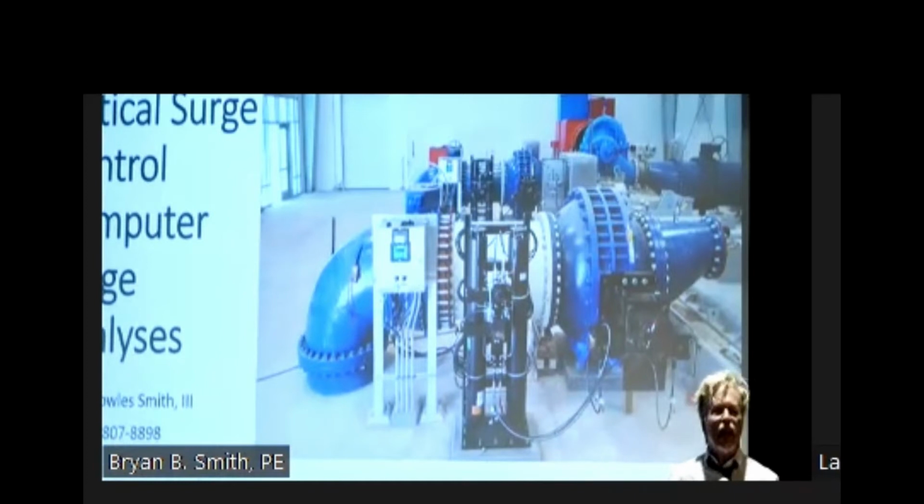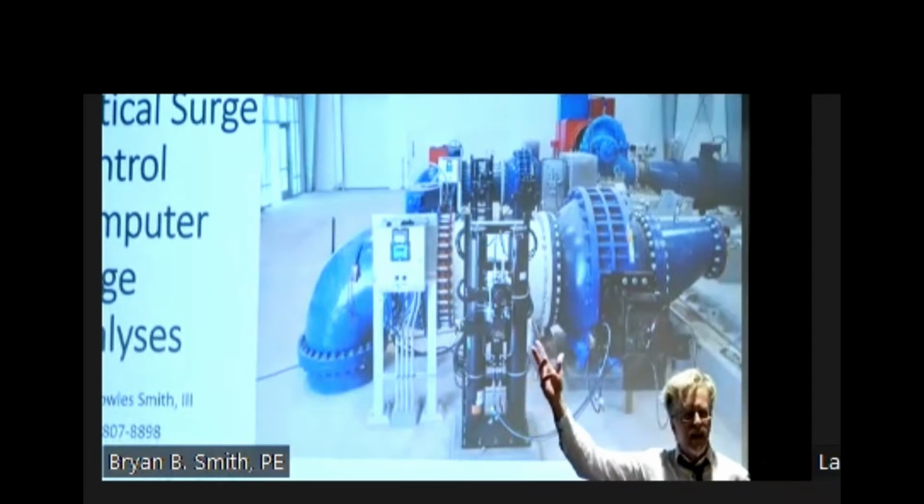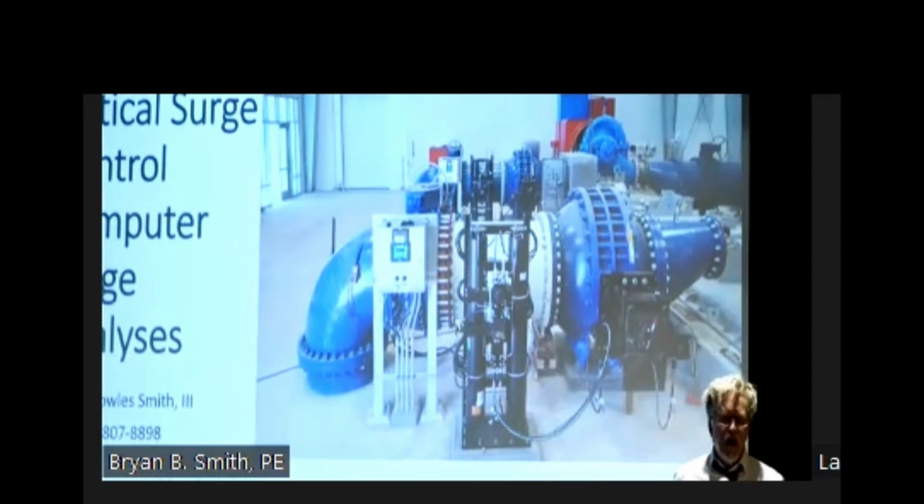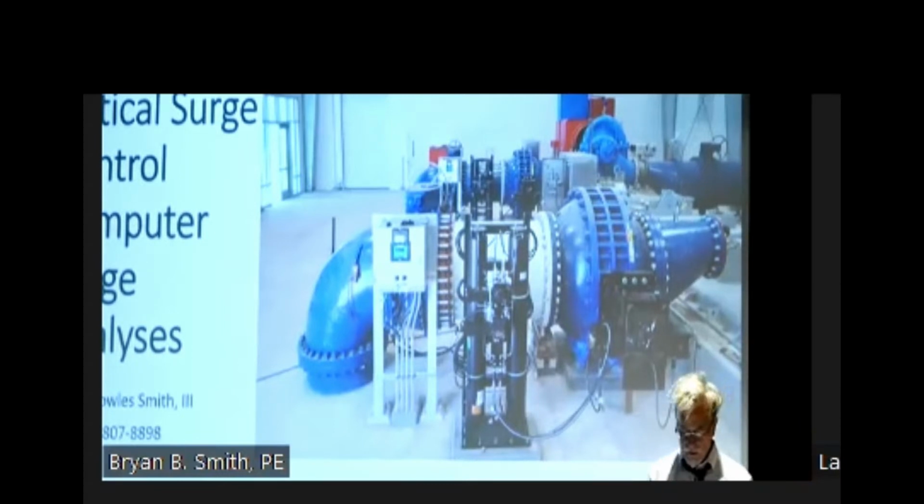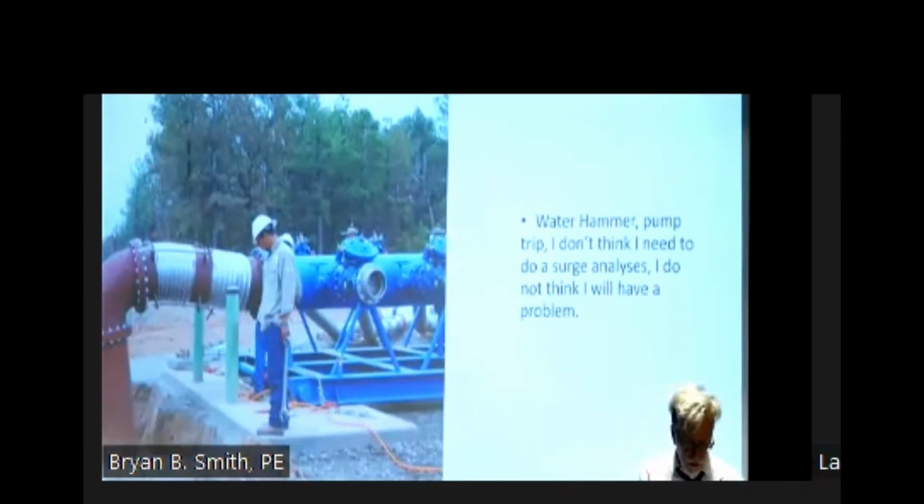Immediately, we're not going to have a transient wave go from the water plant all the way to New Orleans East and come back. Oh no, it's sending energy back immediately. So I need to close this big old ball valve as quick as possible, but I don't want it to slam shut. So I'll design the system with a two-phase closing. So you design the perfect system.